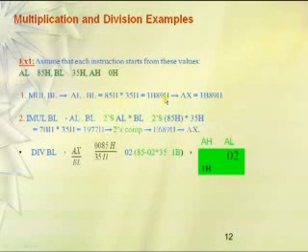Now we have got one result. That result is a 16-bit result, and it is stored inside the AX register. And here we are doing IMUL, which is signed multiplication, between AL and BL. It initially converts AL into 2's complement form, and that 2's complement form will be multiplied with BL. The result is again converted into 2's complement form, and that will be stored inside the AX register.